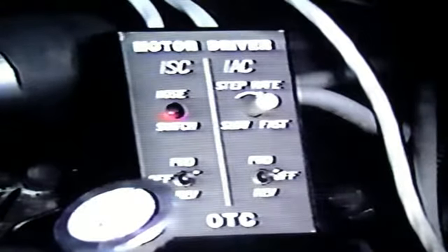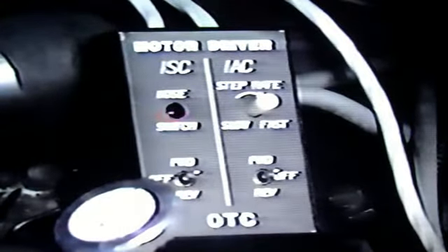We found this the most efficient way to get into power balance testing on cars with ISC or fuel-injected cars with idle air motors. With the tester hooked to the C and D terminals, retract the ISC motor plunger until the carburetor linkage comes to rest on the curb idle screw. After checking the manual for idle speed specs on this engine, you'll want to turn the idle screw according to specs to achieve minimum authority setting. Remember, accuracy is very important in making this adjustment.